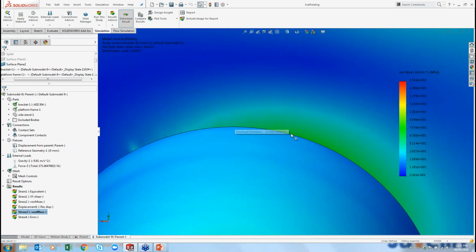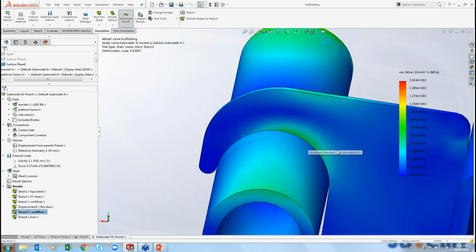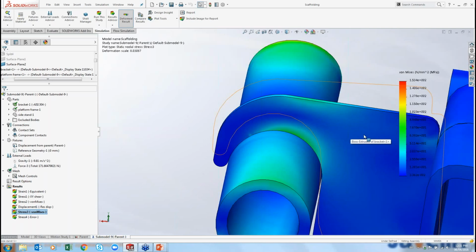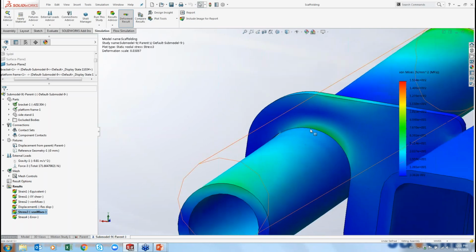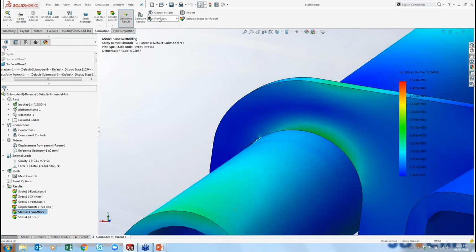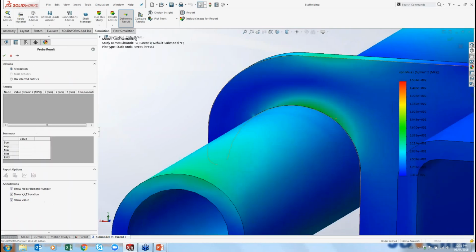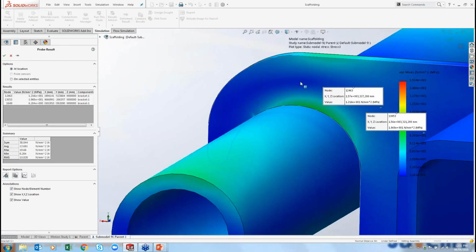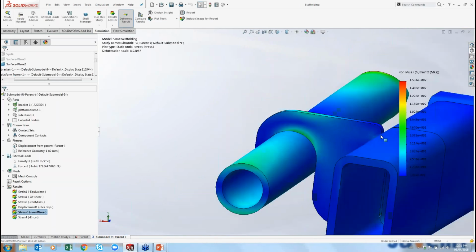Are we just going to end up sort of curling back the edges in here and maybe flattening out or hammering out that outside edge, or are we going to see a yield failure on the entire bracket? Well, in this case, we're safe. We can see exactly where the highest stress regions are, and I can also see that that very quickly bleeds back to a very, very low stress. If I look at the center of that bracket, we're dealing with stresses in the... I'm sorry, much lower, not 150. We're seeing 62 MPa, we're seeing 12 MPa, we're seeing 19 MPa. So very, very low stresses in the majority of the brackets.